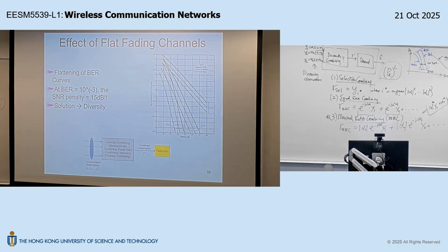And then similarly, for the second observation from the second antenna, you need another RF to convert to the baseband signal, like this, right? Then what do you need to do next? For the same argument, these are analog domain. You don't process the receiver based on the analog domain. You need to convert to digital domain.